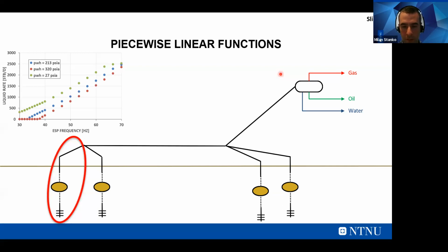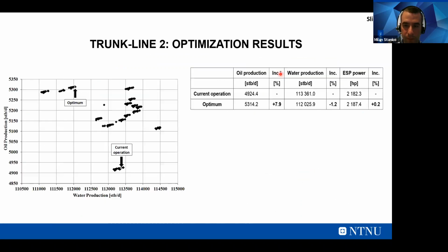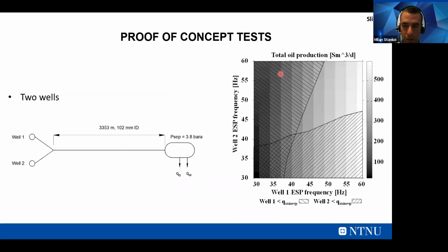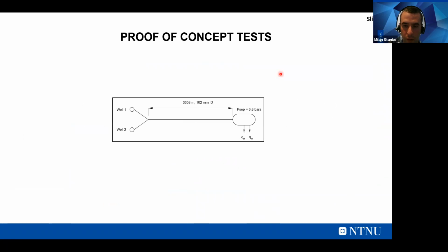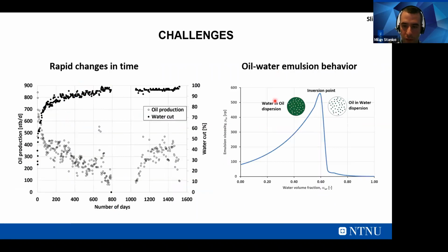It considers slip and emulsion viscosity, depending on the concentration of the dilute phase. I think this typically assumes exponentials. Yeah, this one is exponential. You have two exponential equations, one for this side, one for this side.